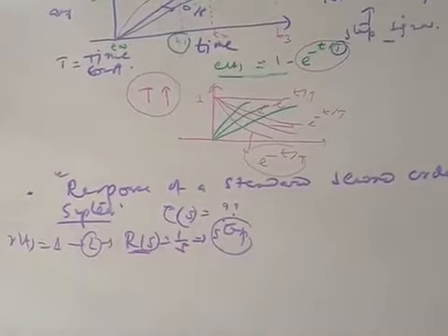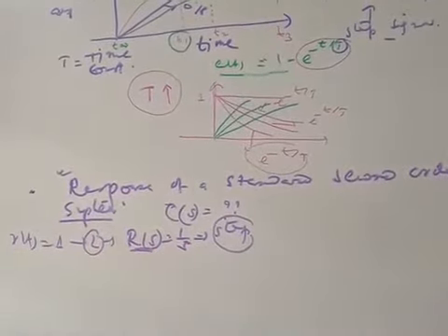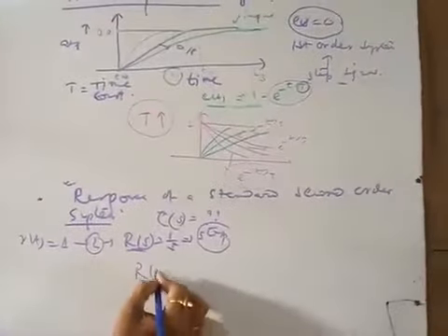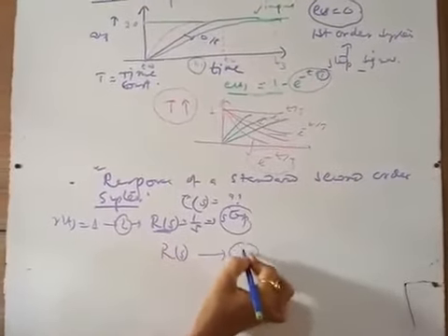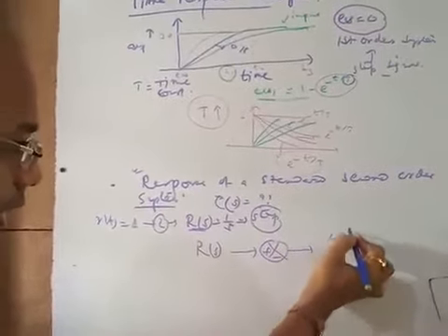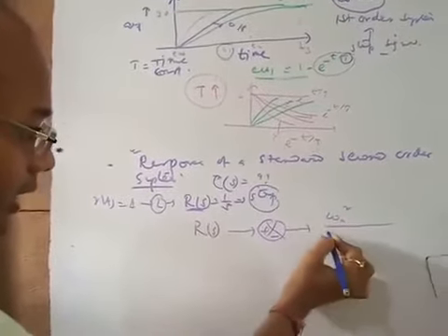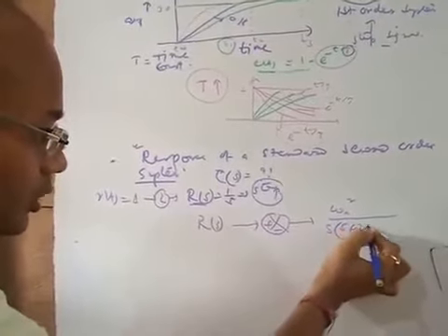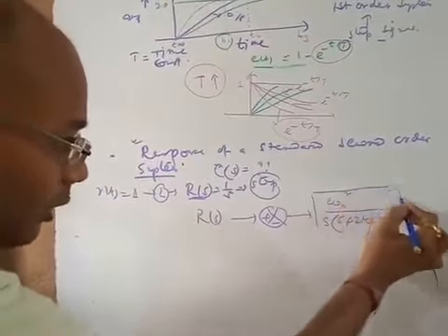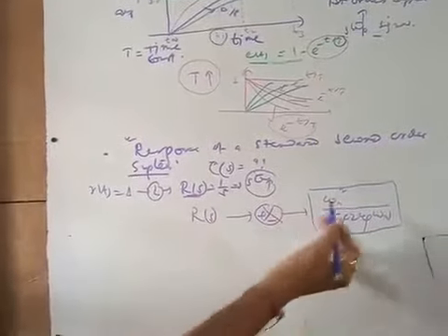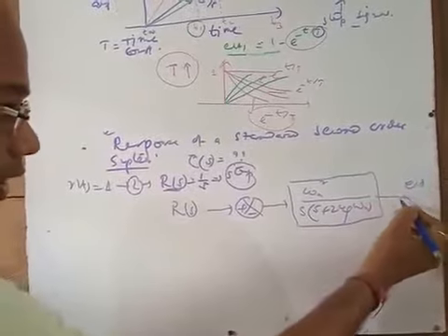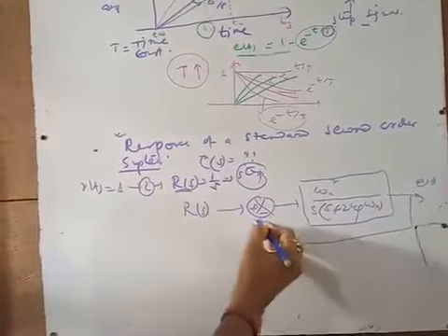Now how does the standard second order system look? For that I am writing here one basic block diagram. This is plus minus, and this is your omega n square by s into (s plus 2 xi omega n). I will discuss in detail the parameters I have written here, like omega n and xi. So this is your C(s), the output signal, and a unity feedback control system.